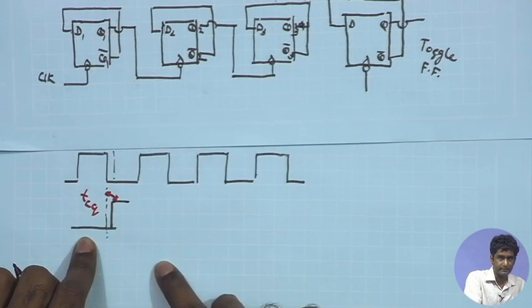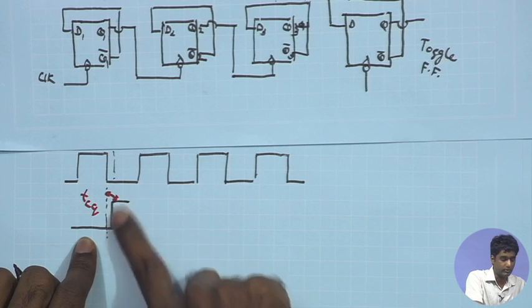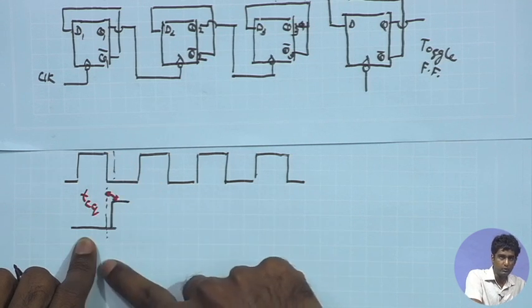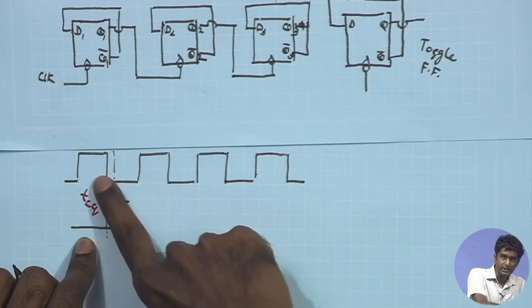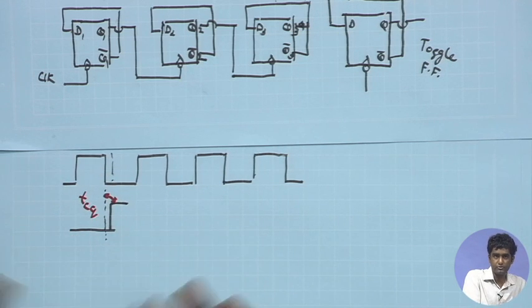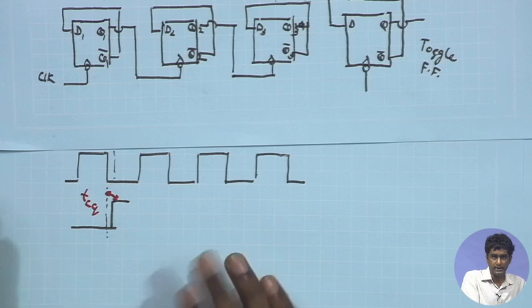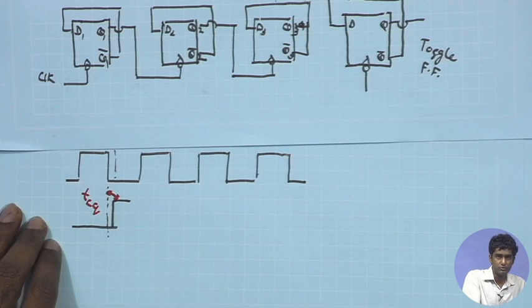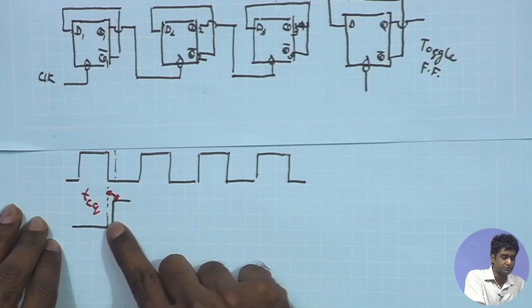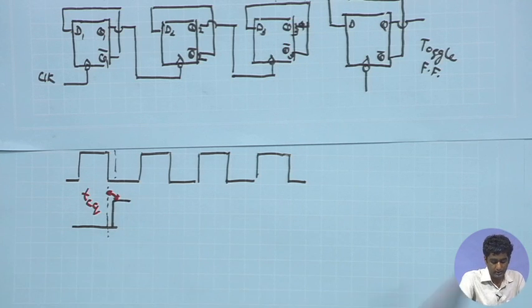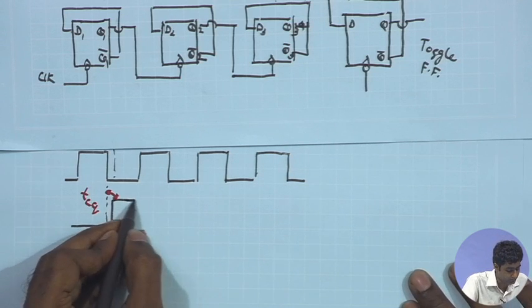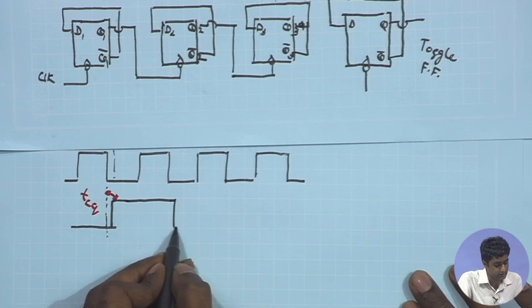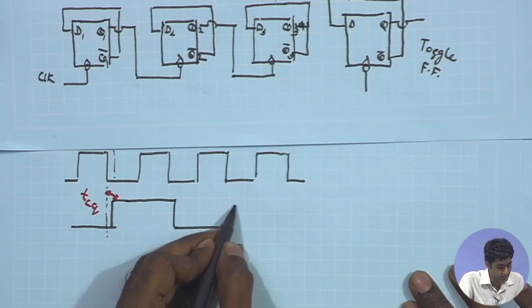to change its state. So, ideally, of course, in our simulation waveform, it should change instantaneously whenever the clock is going low. Ideal flip flop should transition immediately at the negative edge as per our definition, but because of the inherent delays in the circuitry implementing these flip flops, there will be a finite C to Q delay, and as a result, it will be transitioning only after a finite delay. Likewise, after every edge, there will be this finite delay in the transition, from high to low transition as well as low to high transition, there will be a finite delay.